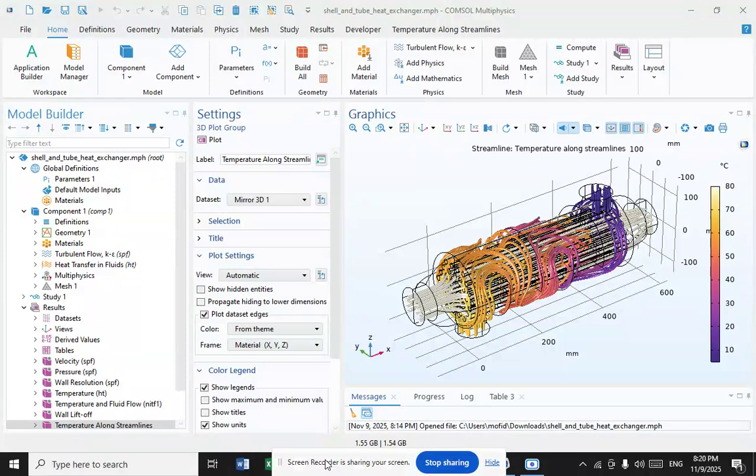And what about the flow arrangement? There are three primary classifications of heat exchangers according to their flow arrangement. In parallel flow heat exchangers, the two fluids enter the exchanger at the same end and travel in parallel to one another to the other side. In counterflow heat exchangers, the fluids enter the exchanger from opposite ends.